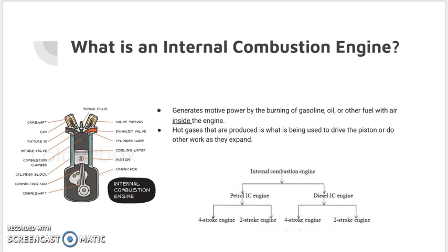When the piston squeezes air within the cylinder, the air inside becomes very concentrated, and since it uses diesel, which possesses a higher energy content, the likelihood of the fuel reacting with the concentrated air is greater. Another way to think of it is when air molecules are packed so close together, fuel has a better chance of reacting with as many oxygen molecules as possible. It turns out that what Rudolf theorized was exactly right, as the compression ratio of diesel is much higher than gasoline.